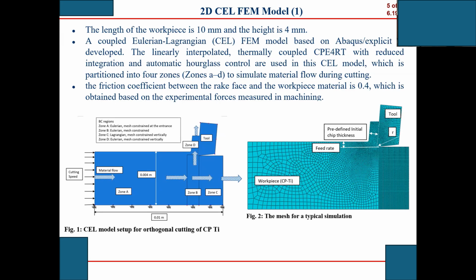However, Abaqus/Explicit is used to solve the dynamic problem. Dynamic problem means that the load applied is so quick that you cannot ignore the dynamic effect. The dynamic effect is that the acceleration and the mass of the points need to be taken care of.